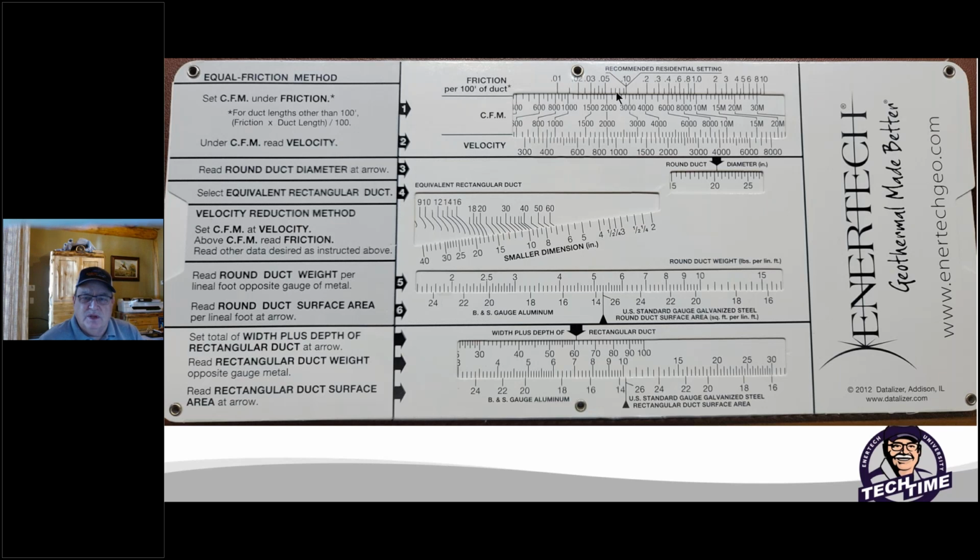One thing that I always did and people do is I only try to design a system between 75 to 100 CFM of airflow coming out each register. That makes systems quieter. Costs a little bit more money, a little bit more material, but you can tout yourself as doing it as a better value to your consumer.